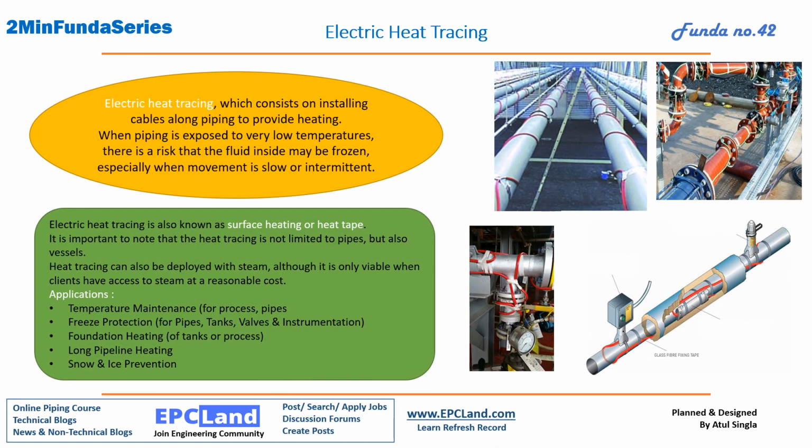Electric heat tracing. If you see, electric heat tracing consists of installation of cables along the pipe to provide heating. Okay, all this cabling will be all around the pipe. If you see all the valves and all the instruments, again this arrangement will be there. Why are we going for electric heat tracing? When piping is exposed to very low temperature, there is a risk that the fluid inside may freeze. Okay, to avoid this situation, we have to balance the heat loss from the pipe with the heat input by the cabling. Once we are balancing this, then the purpose is fulfilled.